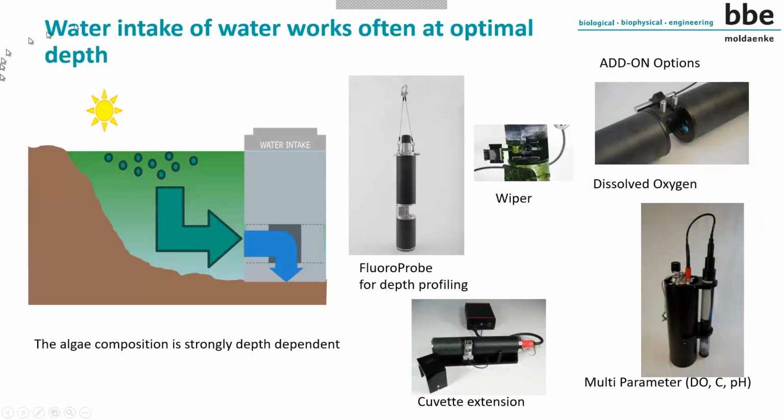The waterworks intake is often in the depths. Yeah, see, the water intake is often not on the surface but in the depths, and the algae composition is strongly depth dependent. So if you only see the surface via satellites or so on, you do not know really what is going on in your intake area. That's the reason they also use fluoroprobes for depth profiling.